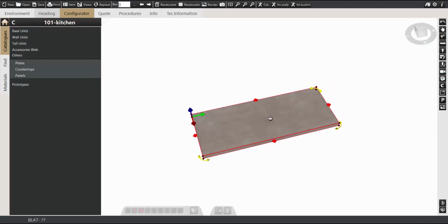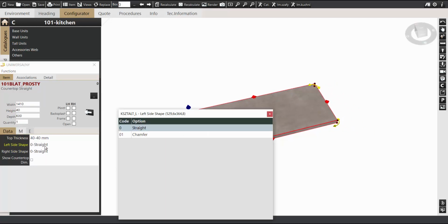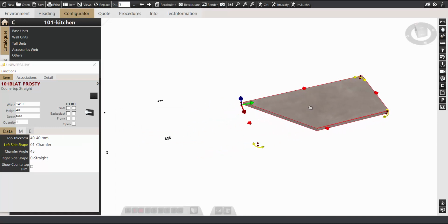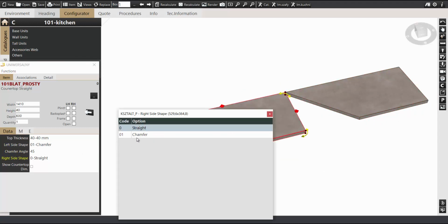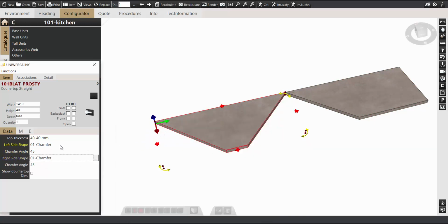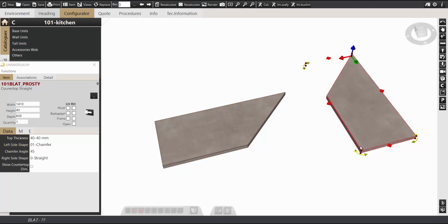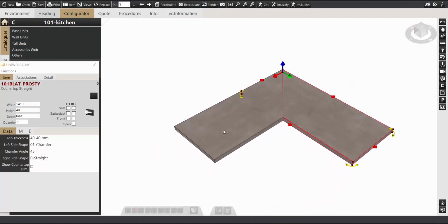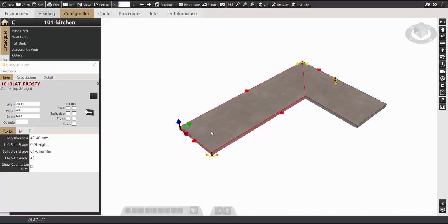Now we start to produce an individual countertop, which may be used for corners in 90 degrees. So we design a corner which is 45 degrees on one plate, and after this we place another one to be connected to this plate later. Editing the single part is very easy. You can change the contour in the way you want it. After this you use the rotation tool showing the angles, and you connect the two plates together. After this you can edit the plate by stretching with draggers or real dimension.